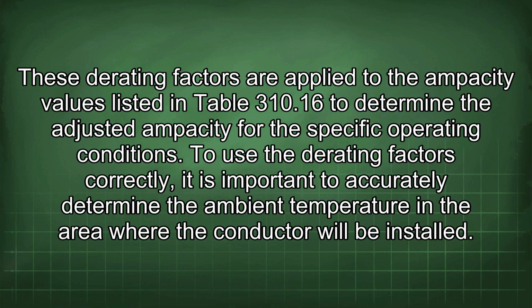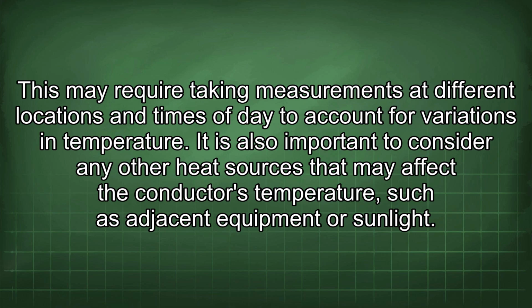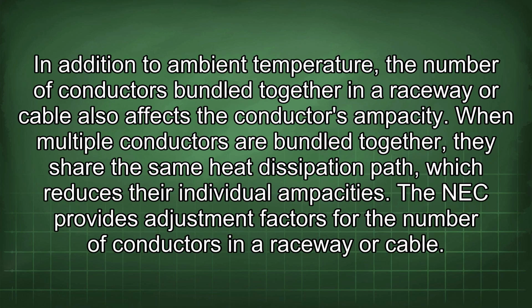specific operating conditions. To use the rating factors correctly, it is important to accurately determine the ambient temperature in the area where the conductor will be installed. This may require taking measurements at different locations and times of day to account for variations in temperature. It is also important to consider any other heat sources that may affect the conductor's temperature, such as adjacent equipment or sunlight. In addition to ambient temperature, the number of conductors bundled together in a raceway or cable also affects